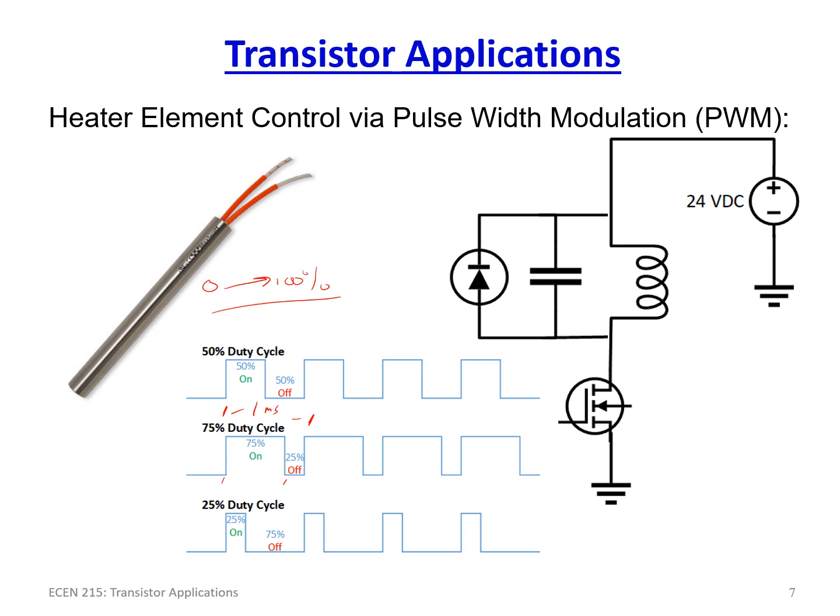Working with things, PWM is heavily used in heaters, even cooling systems. Thermoelectrics use it. This is heavily used in speed control of motors. In fact, when we were talking about H-bridge earlier, you can actually control the speed of a motor by using PWM.